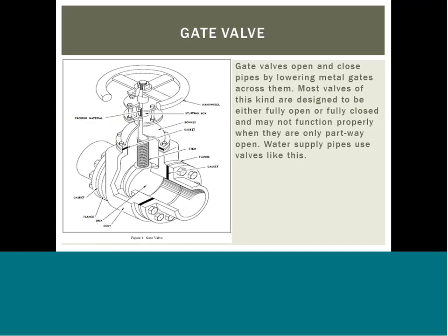Gate valves open and close pipes by lowering metal gates across them and are named after this for a good reason. Most valves of this kind are designed to be either fully open or fully closed and may not function properly when they are only partway open. Water supply pipes often use valves like this.